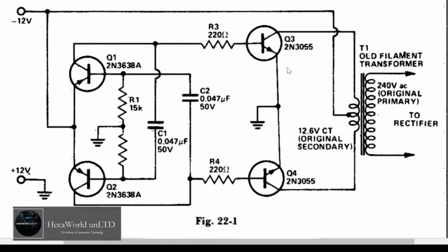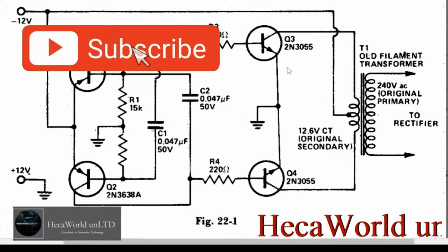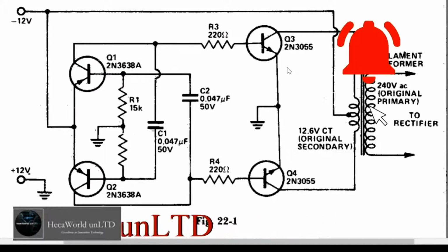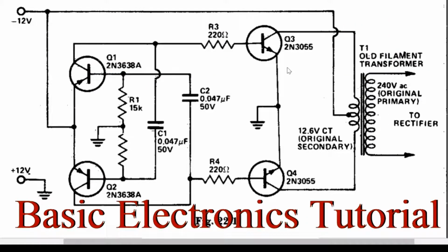I'm going to tell you one more thing about transistors. When you have a 3-terminal transistor and you want to check the emitter, base, and collector, you put your probes on the 3 terminals, taking 2 at a time. At one point, you're going to get a deflection. And by the end of the day, you find out that with one probe on one terminal, you can get deflection on the other 2 terminals, or pinouts. The common of those pins is the base. The other 2, one will be the emitter and one will be the collector.